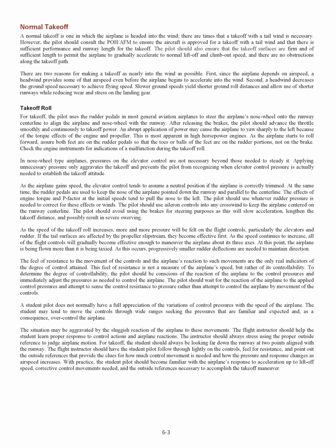Normal takeoff. A normal takeoff is one in which the airplane is headed into the wind. There are times that a takeoff with a tailwind is necessary. However, the pilot should consult the POH/AFM to ensure the aircraft is approved for a takeoff with a tailwind and that there is sufficient performance and runway length for the takeoff.